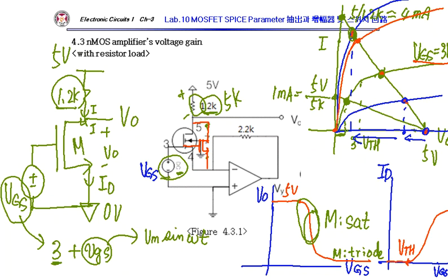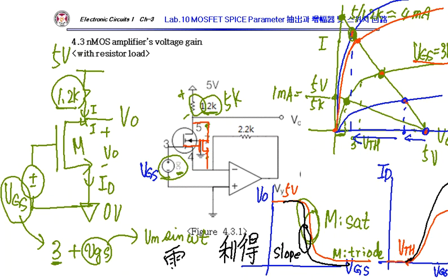So here, if I put 2 current here, my VO will drop more sharply because of the large voltage drop across this 1.2K resistor. Current will be increased again, right? Twice. So I have a higher gain. That slope determines my voltage gain. Okay, voltage gain. This is gain, right? My voltage gain.